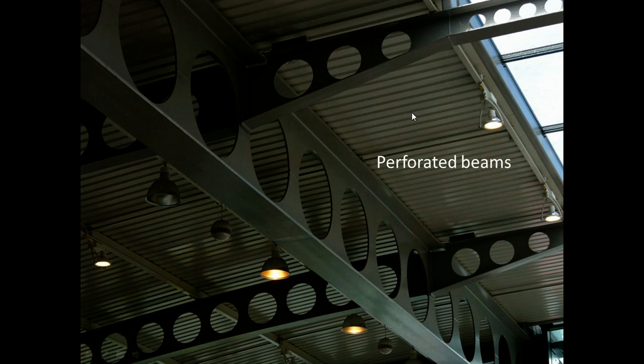You're actually now also looking at the underside of a folded plate floor, which links all these major beams together. It's a nice image in a way, because you can see the whole hierarchy of construction is actually visible. This is the major beam taking its load to the ground at each end here. This is the secondary beam, and it's cantilevering. You can see they're cantilevering off at this point to carry a little bit of floor or roof up there, and then these are rods running through, and then they're connected that way. So there's a hierarchy of structure.